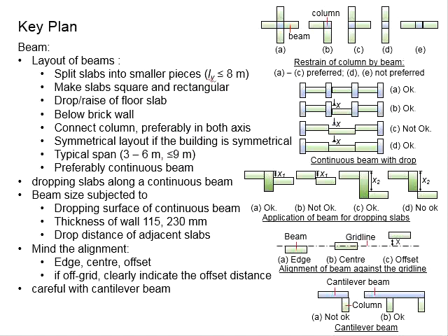The reason is when your beam span is more than 9 meters, you need a significant height of the beam, which normally will cause a problem with the headroom as well as the space available within the ceiling. This will require an additional column to reduce the span of the beam so that it falls just nicely within the typical size used in the industry.